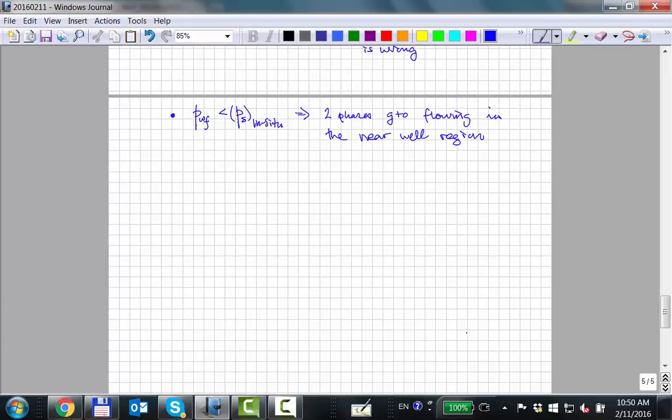So the problem is that the relative mobility of gas will be different than the relative mobility of oil. So if gas comes out of solution from the oil, what could theoretically happen, it almost never happens, is that you would think the gas starts flowing faster than the oil, so the gas-oil ratio that you collect is not 500 cubic feet per barrel of what's in situ, but you might get 550 because you've got this local gas coming out of it.